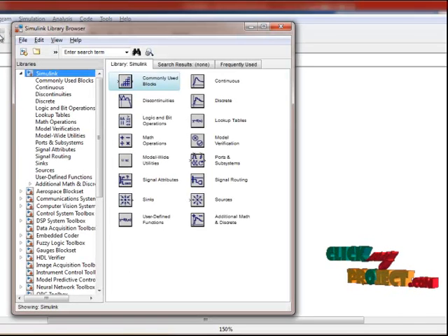Here this is the Simulink library browser, where we search for the components our process needs. After connecting as per the design in the paper, we have the DC sources and bus systems, the converting process, input DC source voltage measurement and current measurement, and then the DC load, DC power load, resistor load, RLC load. Whatever devices we want to connect as per the process, we search for all the components from here to complete the design.